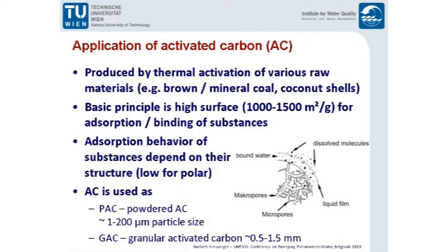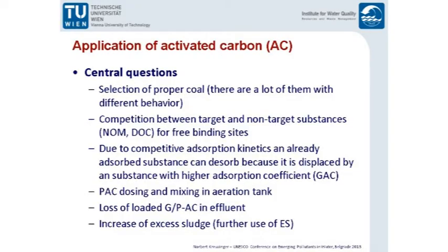So one of them is the activated carbon. You know about the application of the activated carbon, high surface areas. Two aspects applied, as powdered form and as granular form. And there are different options that I will show you briefly how you can implement. Generally, activated carbon is a very potent technique, but does not solve all problems. Neither does the ozone, nor is it really easy in the technological approaches. So there are some problems that we have to solve when we want to introduce the technology into full scale.